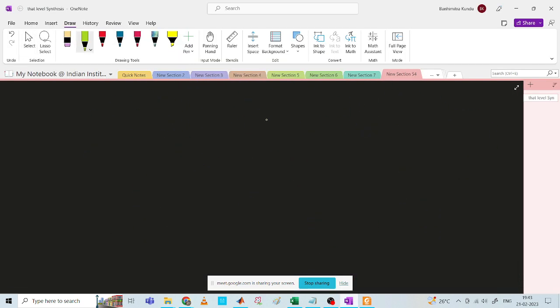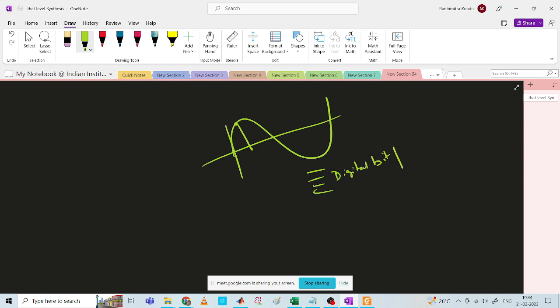You have one input signal, which looks like this. Now what a normal A to D converter does is it takes one sample and converts it to a digital bit pattern. But delta sigma stores this bit pattern, and it calculates the difference between the last analog value and this analog value. It calculates only the difference.